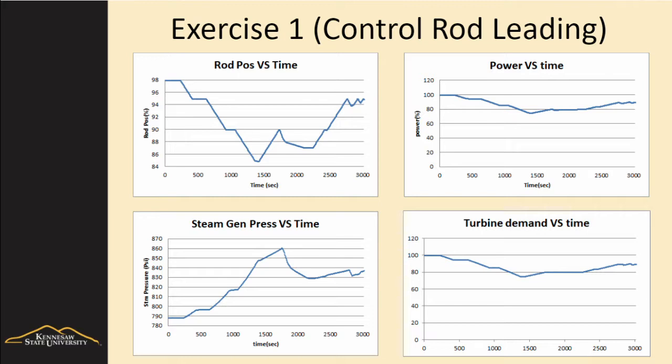All reactor operations such as the turbine demand, pressurizer level percentage, and the temperatures change as a direct result of the changing reaction rate that results from the change of the rod insertion levels. Reactor power does not change linearly with control rod control, as the reaction rate does not have a direct linear relation to the control rod insertion percentage.